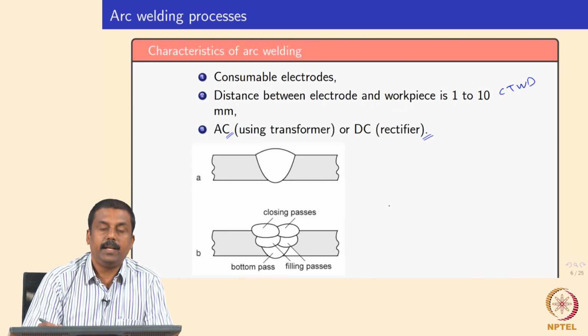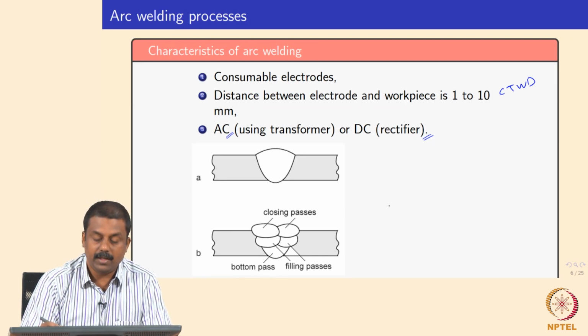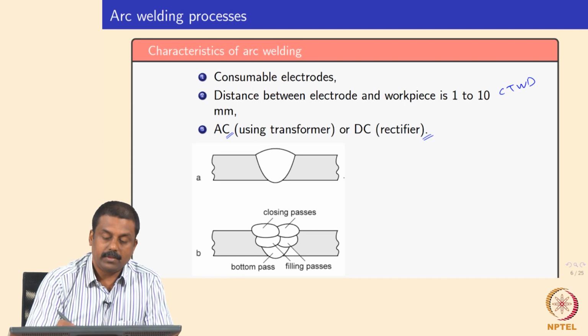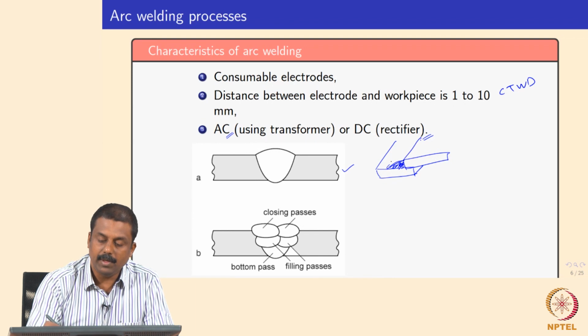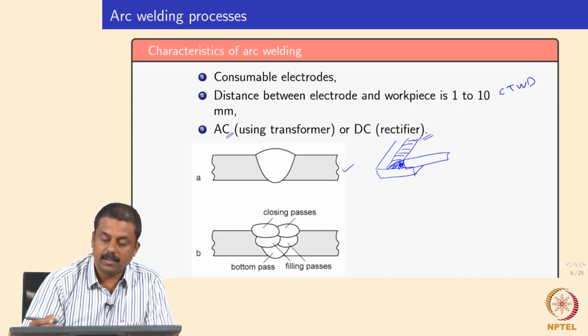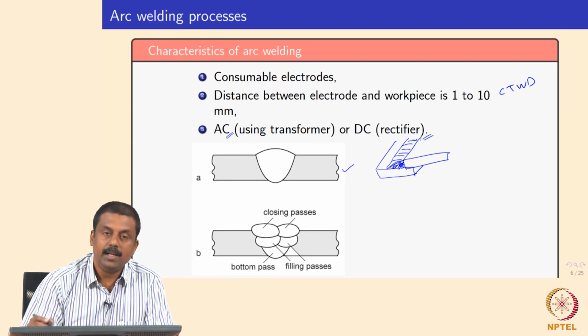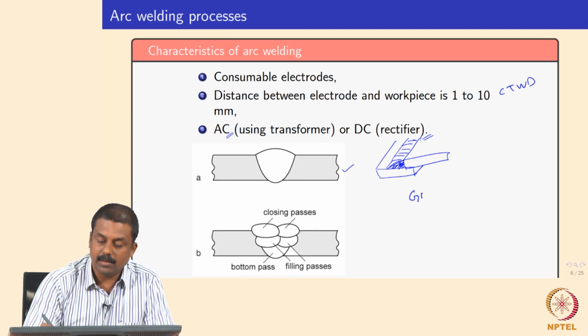Generally in welding of automotive steels, if you are using GMAW, in most cases we will be doing a single pass, and in some cases we may also have to do it in an overlap configuration, like in a lap joint in a fillet mode. So we will be doing welding in overlap configuration. This is the most preferred mode of welding, especially if you are doing GMAW brazing.